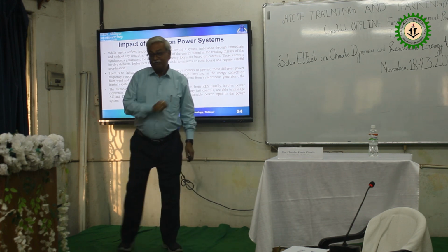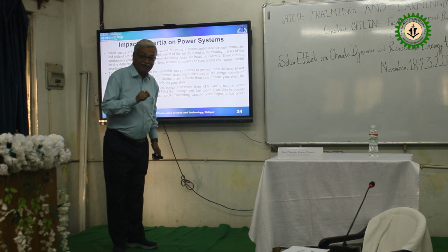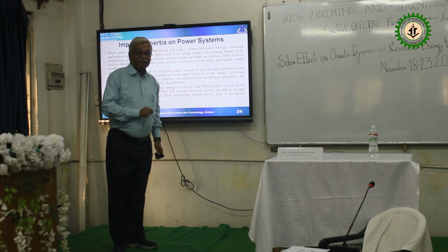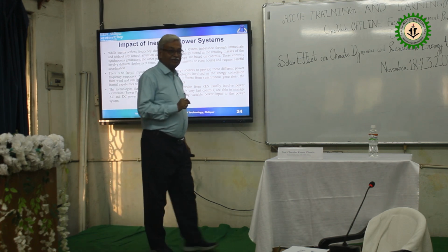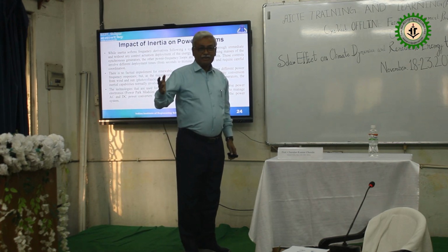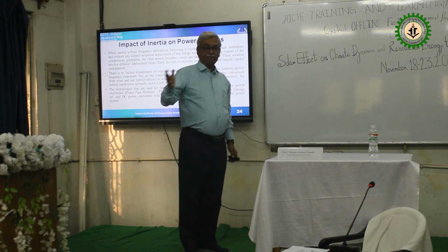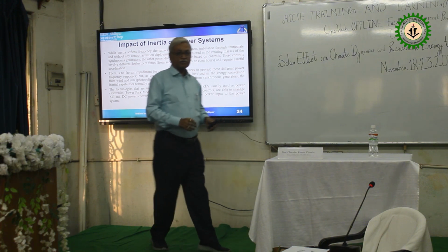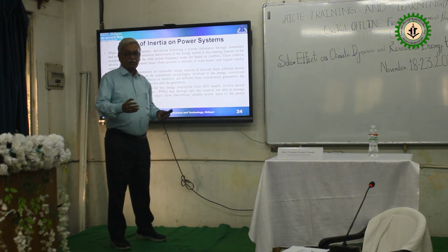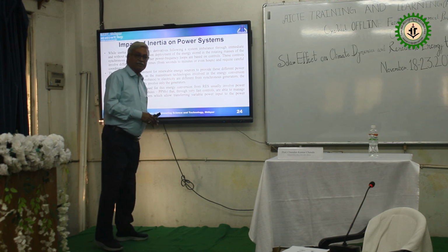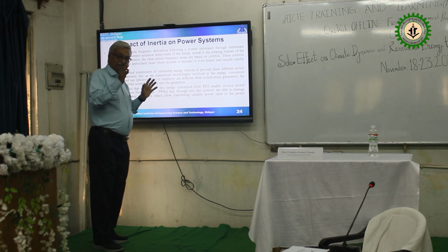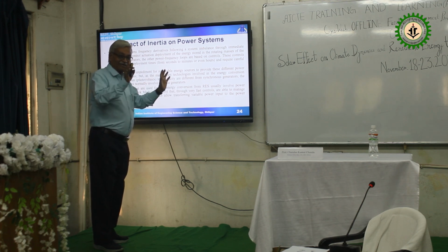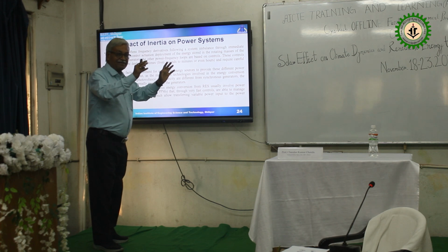So 4 or 5 seconds for an electrical power system is a golden span, and we have to take care of it with the help of synthetic inertia or virtual inertia. Peak storage, supercapacitors, pumped storage: these are important devices which can play the role of synthetic or virtual inertia. They do not have physical rotational inertia. It does not mean that the inertia will give some kind of rotation.